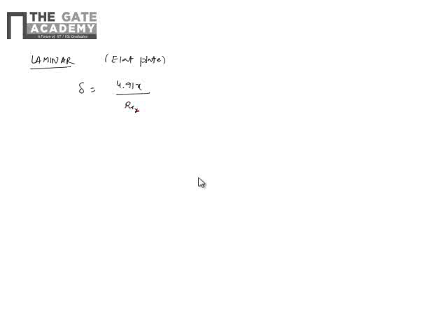So this is how it turns out for the boundary layer thickness for flat plate laminar flow. There are two things of interest: the boundary layer thickness, how big the boundary layer is, and what is the effect of the boundary layer. That is captured in the local friction coefficient, because once you know the local friction coefficient, you can get the drag force. That's what we discussed, right? So this is Re_x to the half, and all this is valid when Re_x is less than 5 times 10 to the power 5, because that is the demarcation.